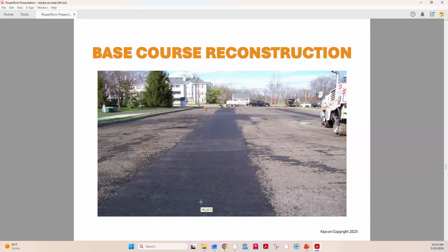So you've got two things going on. You've got a natural seam there and you've got a flow line there. And we see a lot of deterioration in these areas in older pavements. So oftentimes this needs to be milled out and this needs a full depth reconstruction to restore that pavement structure again, so that you do not have those cracks reflect up through your new pavement.